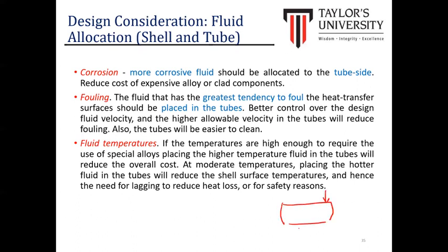We have the fluid inserted into the exchanger, a main fluid effluent from the process, and we have another fluid from the utilities. It depends on the application, whether cooling or heating up the process effluent fluid. For example, if we have maybe acidic, and also we have the cooling medium, cooling water. So for example, how can you decide whether cooling water or acidic to be inserted in the shell or tube?